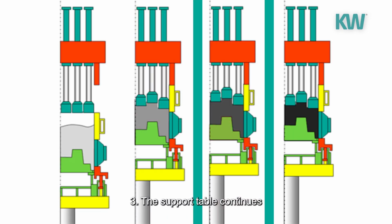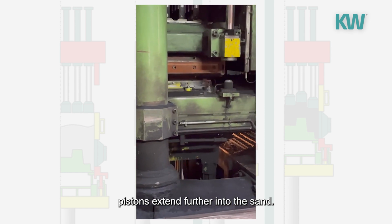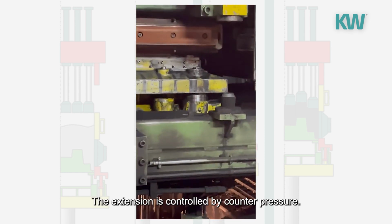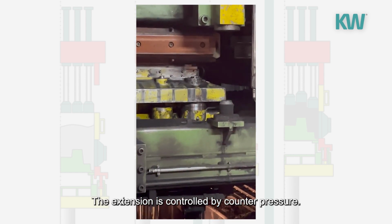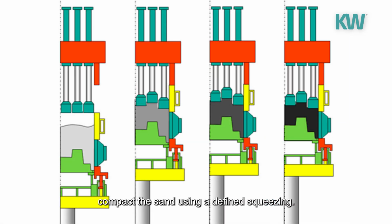3. The support table continues moving up while multiple compression pistons extend further into the sand. The extension is controlled by counter pressure. In the final compaction step, multiple compression plates continue to compact the sand using a defined squeezing.